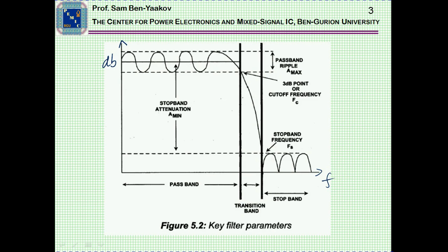Now, here's a typical filter in which we can see that there are some characteristics that we are interested in. For example, we like to have a certain degree of roll-off, that is how fast it attenuates the frequencies above a given point, the ripple that it might have, and then some of the residual response beyond the frequency at which there is a cutoff.